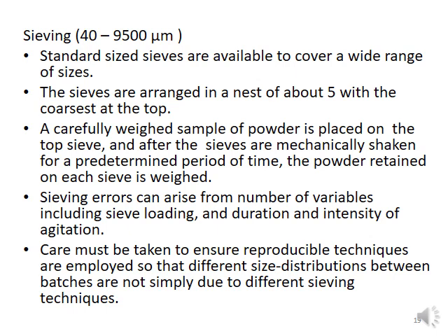time. The sieving errors in the method can arise from a number of variables including sieve loading. The sieve loading should be constant because changing the loading will affect the results obtained. Duration and intensity of agitation can also affect the sieving method. Care must be taken to ensure reproducible techniques are employed so that different size distributions between batches are not simply due to different sieving techniques.